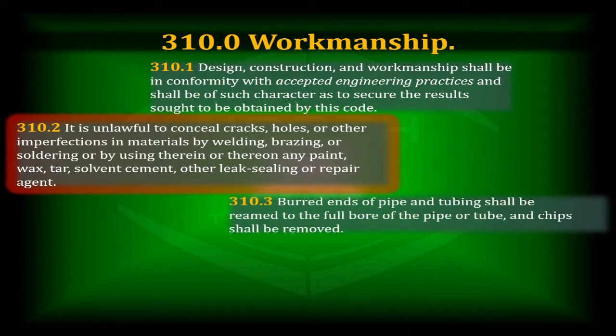310.3, burred ends of pipe and tubing shall be reamed to the full bore of the pipe or the tube, and chips shall be removed.